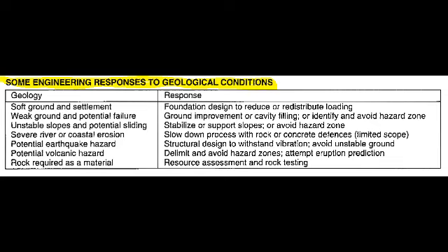Before the construction of a civil structure, we need to consider the geology of that area, and some engineering responses to geological conditions. Geology: soft ground and settlement. What you have to do is design foundations to reduce or redistribute loading. Weak ground and potential failure: ground improvement or cavity filling, or identify and avoid the hazard zone.